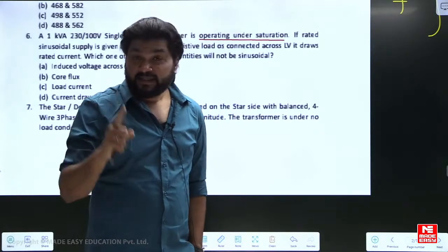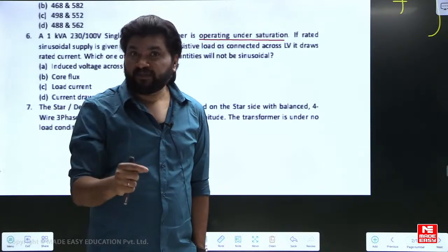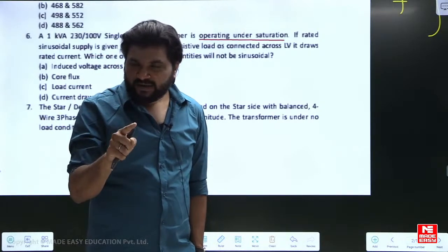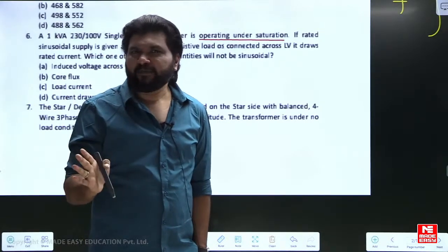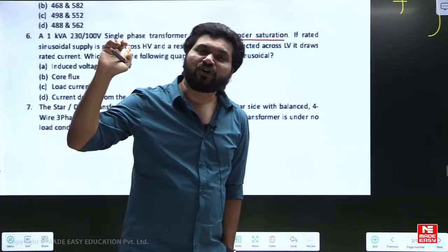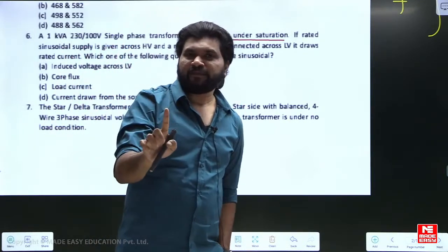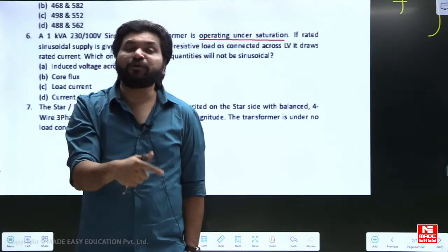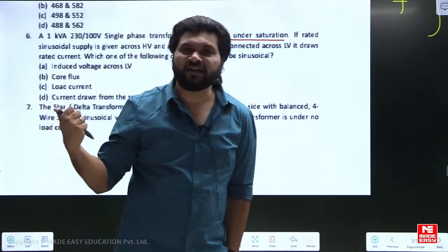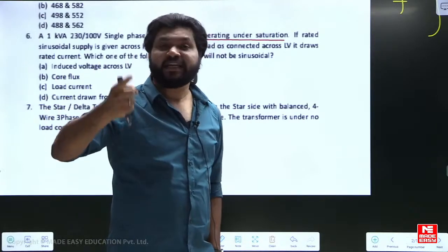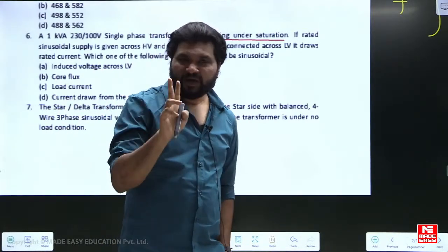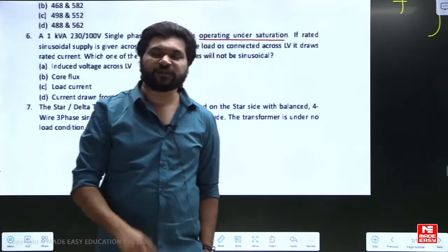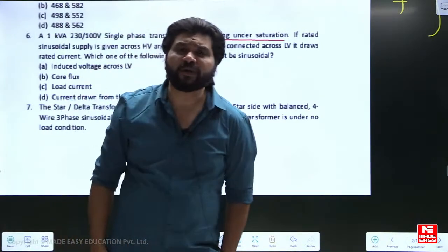Then third harmonic current circulation in the primary will manipulate the sinusoidal current drawn by the primary first. First the current drawn is sinusoidal. Now third harmonic current will be superimposed on sinusoidal current and make the current peaky in nature. This is what you will see in the excitation phenomena topic in transformers, just before the three-phase transformer topic.